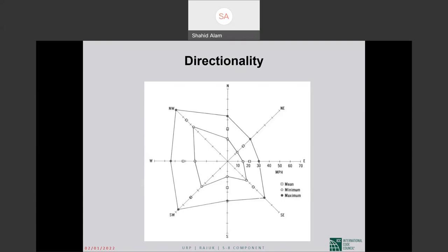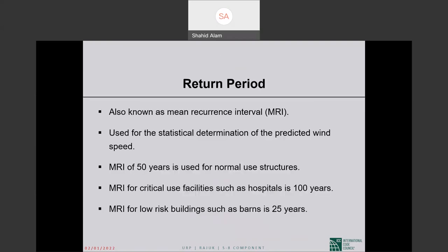I told you the entire story yesterday. Okay? So the introduction of K sub D in the equation for Q was accompanied by the increase in the wind load factor in the strength design load combination from 1.3 to 1.6.